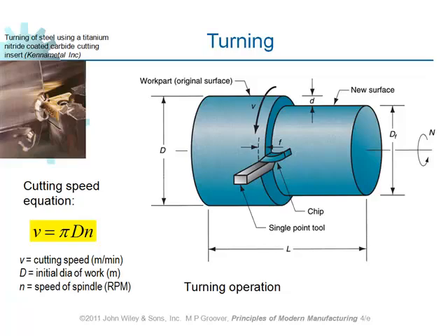And this equation here is used in order to relate cutting speed to the initial diameter of the workpiece and n, which is this n. Here in this equation, I should have made it capital N, but anyway, n is the same n. Okay? Revise it to capital N so that you don't get confused in your lecture slides. So n is the spindle speed, which is RPM. D is the initial diameter of the workpiece, and V is the cutting speed. Indeed, this n in most textbooks has got lowercase n. But in the textbook that we are using, it is written making use of capital N.